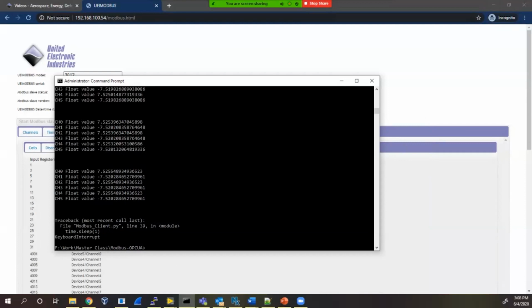And that's it for Modbus. So let's look at if any questions have come in. Okay. Is it possible to get high sample rates, say 50 kilohertz through Modbus? Intrinsically through Modbus alone, no. It can't handle that high data rate, especially because you have a master that has to poll the slave.